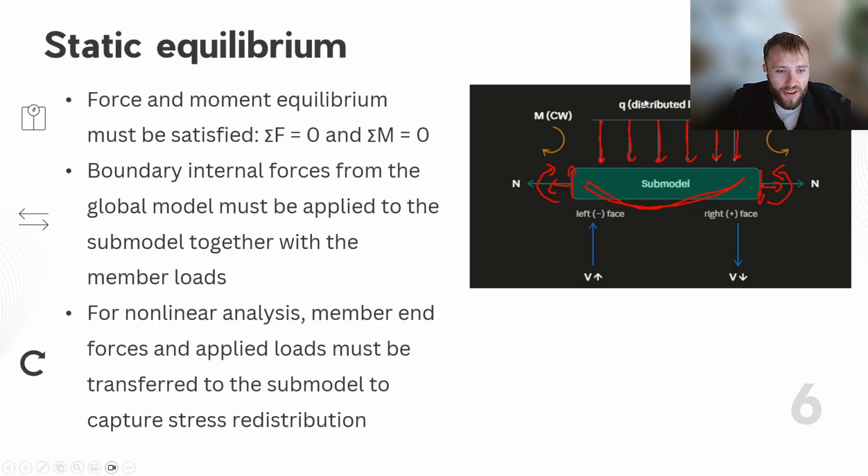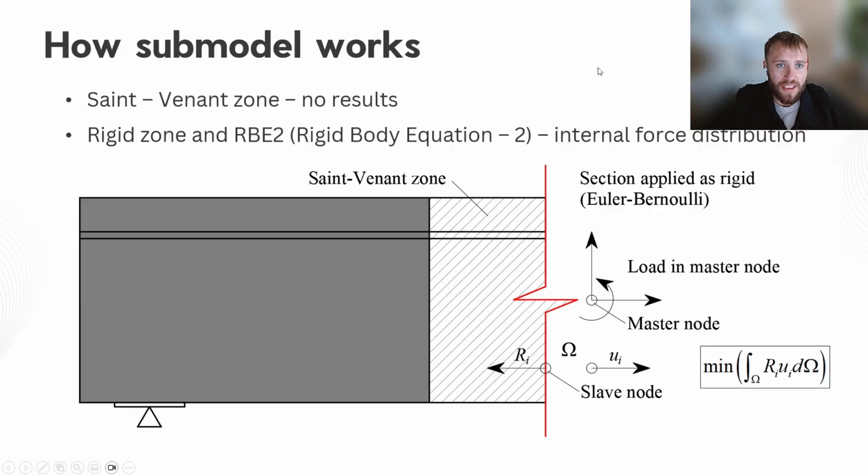So for nonlinear analysis, the member forces must be applied and transferred to the submodel, also with the loads as I mentioned. We are taking advantage of forces because for nonlinear simulations the stiffness is changing, so it is highly recommended to utilize forces rather than displacements for stress redistribution. And this is what we actually have in IDEA StatiCa 2D Detail.